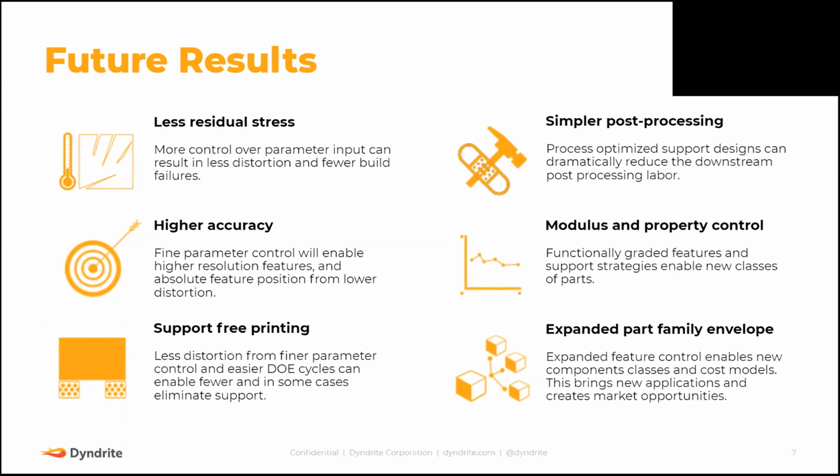Yes. So the way the industry is typically coming from the design for additive background, the way the industry has tried to simplify things is, for example, for a horizontal through hole, what's the maximum diameter you can do? Or for a totally horizontal overhanging ledge, what's the longest span you can do?